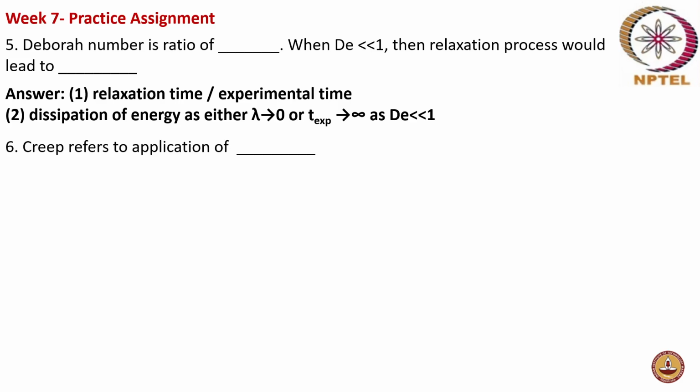Next, creep refers to application of dash. What does the creep experiment refer to? What do you apply in a creep experiment? So, in a creep experiment, a constant stress is applied, and you find out what the strain is as a function of time.